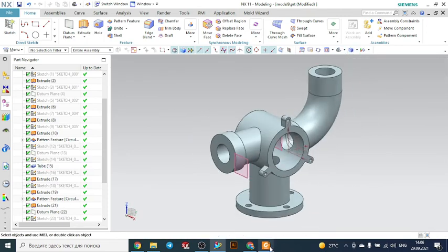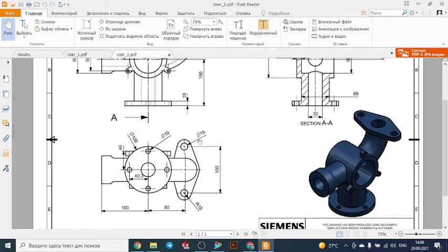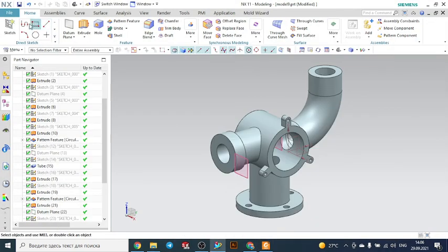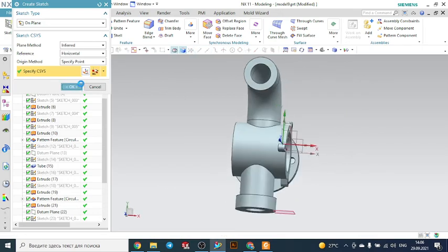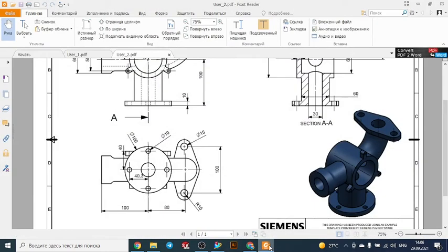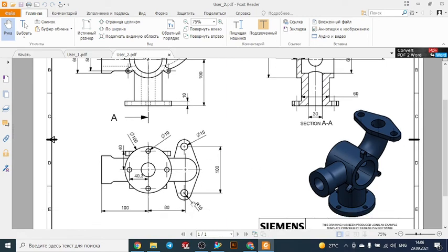This is the system, the element. One more thing that we have to make here, this element on the top. Let's go on with this sketch, this face. Okay. So draw the circles here firstly with the radius of 15.